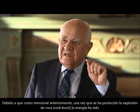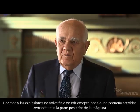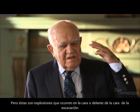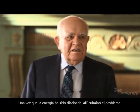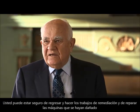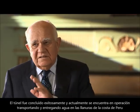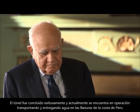Because, as I said earlier on, once a burst has occurred, the energy has been dissipated. It won't reoccur, except for a little bit of after-activity behind the machine. But these are bursts that occur at or ahead of the face, and once the energy has been released, that's it. You're quite safe to go in there and do the repairs and repair the machine. And the tunnel was successfully completed and is now in operation, delivering water to the coastal plains of Peru.